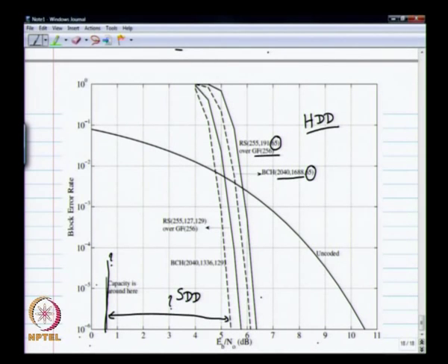Any other question on these curves? Okay, so at this point we have done some general background on soft decoding, and then we have seen some general ideas on how to do suboptimal soft decoders, and then how these classical codes do when you look at them from a coded modulation point of view. What is the coding gain that they provide? How far are they from capacity?